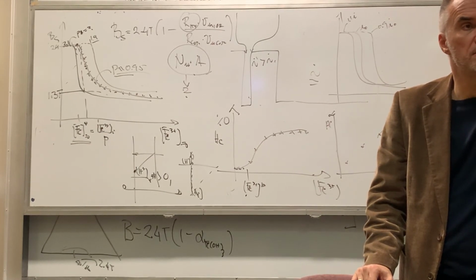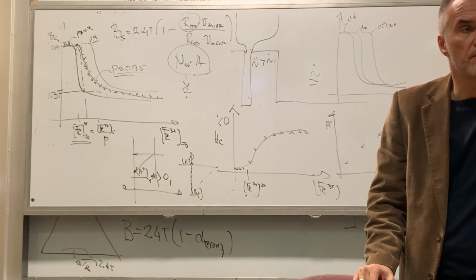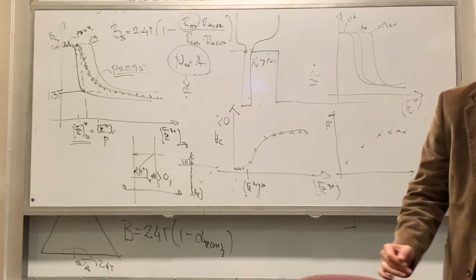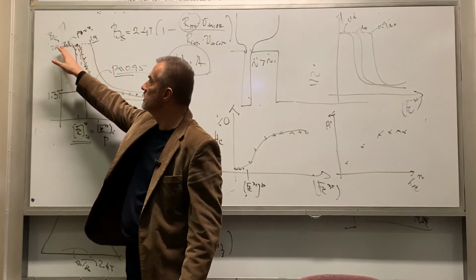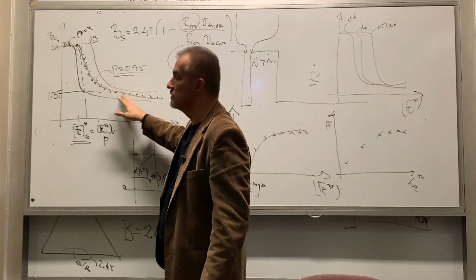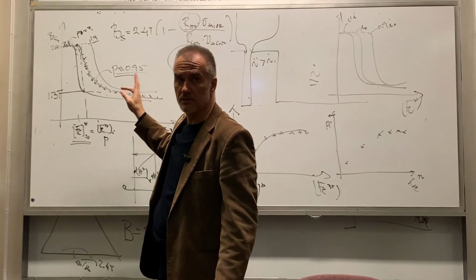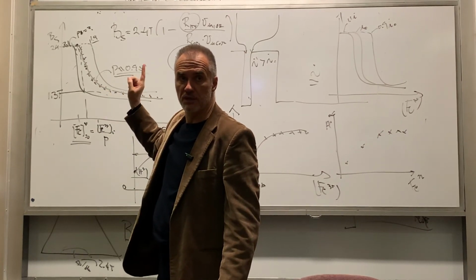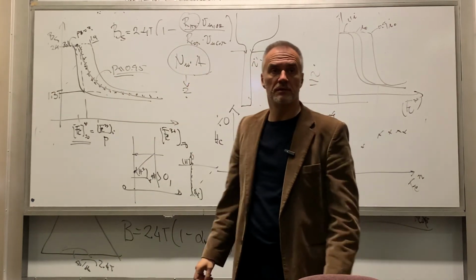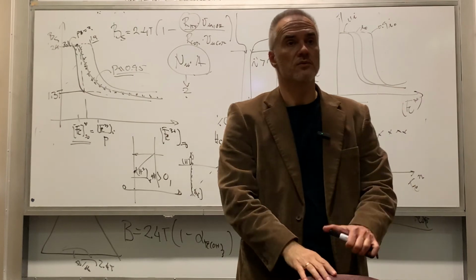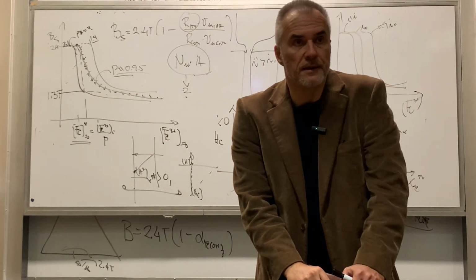How do you get the E value? Since we have two unknowns, how do you get the model? Because we get the rate equation, but it has two unknowns, right? So fit the E value. Yeah. But you have a bunch of experimental data, right? And you fit your model to experimental data, and you extract these two fitting parameters, P and A, okay? That's how you learn your process, right?